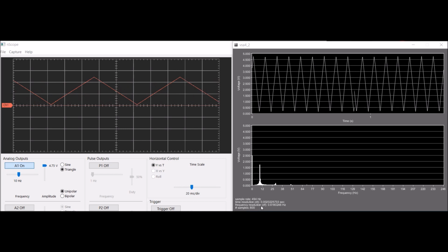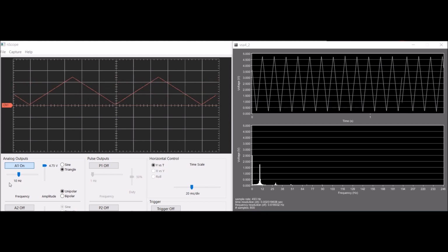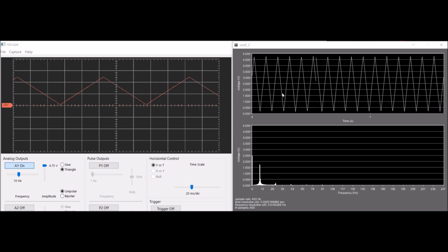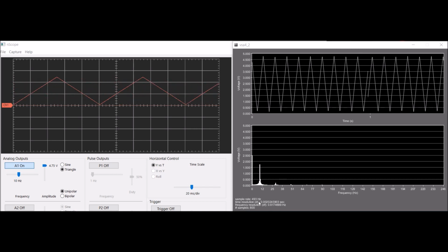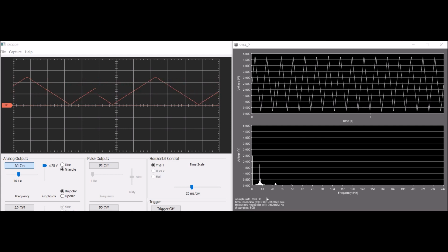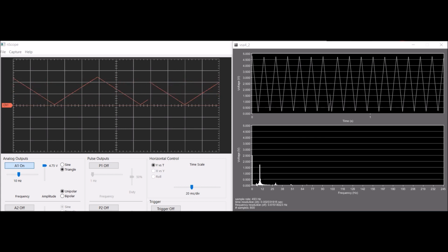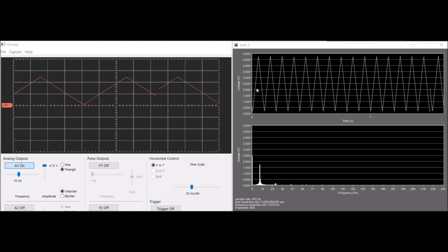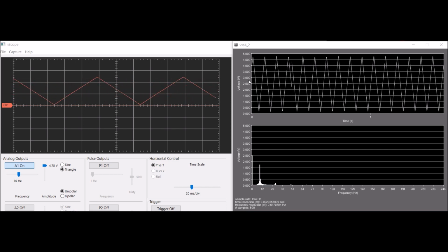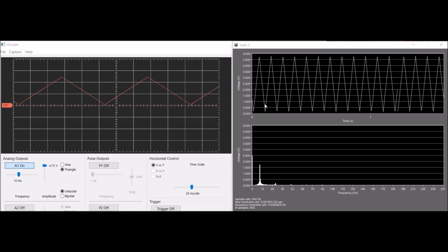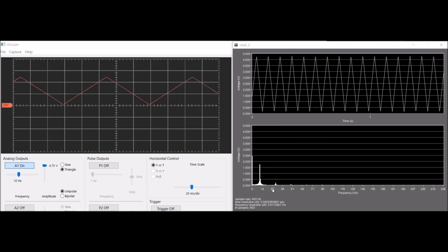This is the triangle wave for exercise 2. We can see that it's set to 10 Hz as a frequency on the nscope. The processing window also outputs a triangle wave, as seen here. The sample rate is about 500 Hz, as seen in the bottom left. So the signal is aliasing at about 10 Hz, also seen around here in the bottom left. With a maximum voltage of roughly 5, you can see that one sample is output every other peak. However, just like the nscope, the voltage maximum is about 4.75 volts.